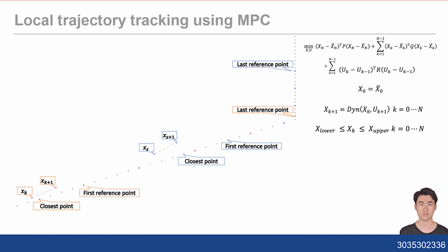Then we pick a reference point every several points. The reason why we use reference points and select them on a relatively large scale is that we need to keep the real trajectory closer to the planned path and detect the turning point early to avoid sharp turning. You can see that there is an obvious turning motion at time step s.